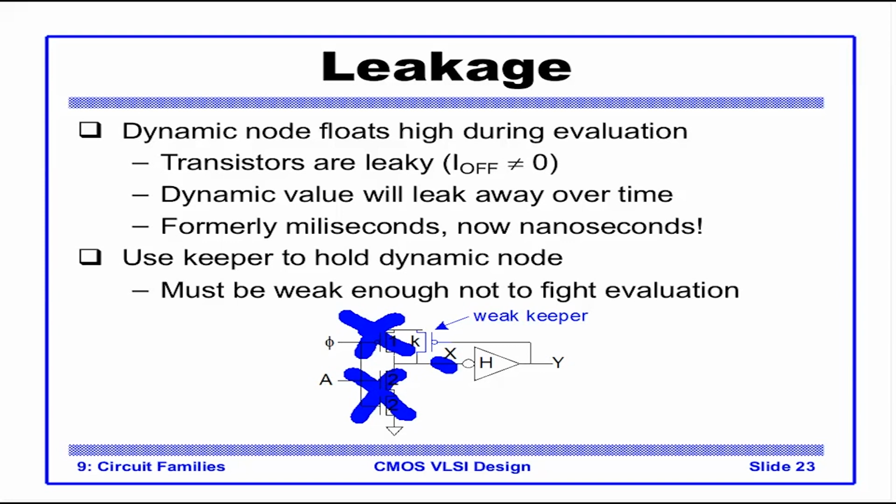A is 0. So now X is kind of a hanging one. We need to keep feeding X to VDD. And how do we do that? We invert X, if the inverter is already there. We invert this and give the output to a PMOS connected to VDD. Now X is 1, Y is 0, this PMOS is on. So now it keeps charging X. In this case, X is not floating and it keeps on charging to VDD for the complete evaluate phase. So we are fine, it will not leak. So this is one problem we have to solve in domino or dynamic gates.